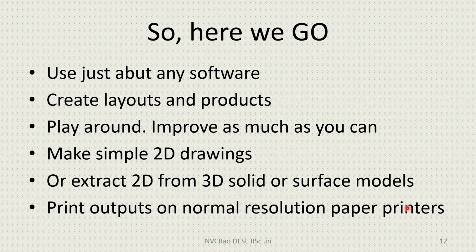In case there is no calibration mode, you need to print a small square, a grid. Typically if you are using an A4 printer, a minimum of 200 by 285 millimeters is available for printing. 200 by 285, because the normal size is 210 by 297.